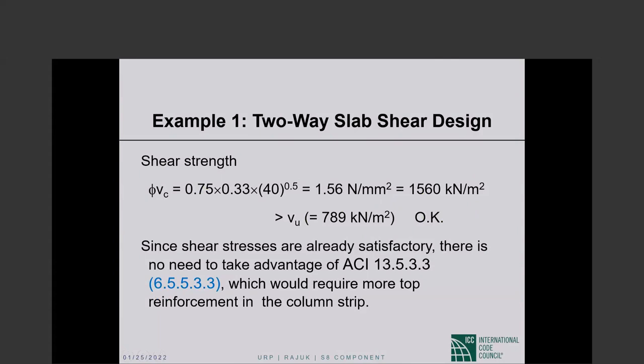Okay, and then I'm saying that we carried out this computation. This is very important. Our calculated value of gamma sub f is 0.62. We use that value, and that gave us a gamma sub v of 0.38, and we have no shear problem.